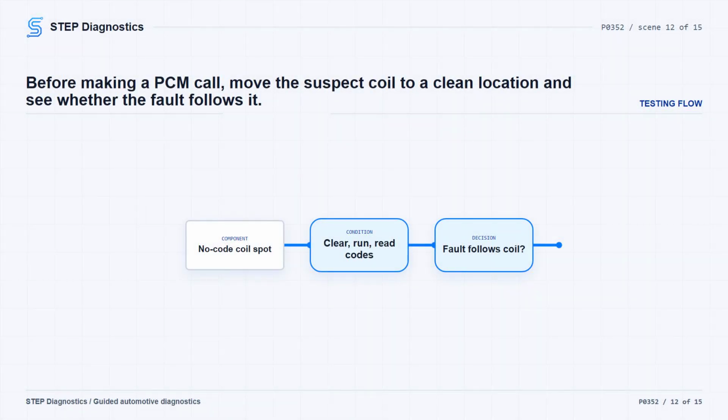Before replacing a PCM, determine whether the ignition coil is the cause of the driver failure. An internally shorted or damaged secondary coil circuit may be the reason the PCM coil driver failed, so do not replace the PCM without checking this first. Remove the ignition coil controlled by the driver that's set P0352 and install that coil in another coil location that did not have a code set against it.